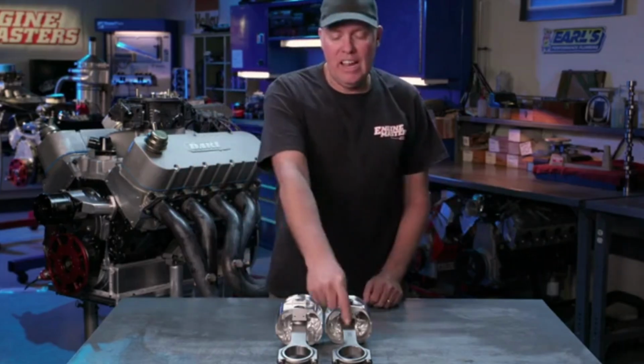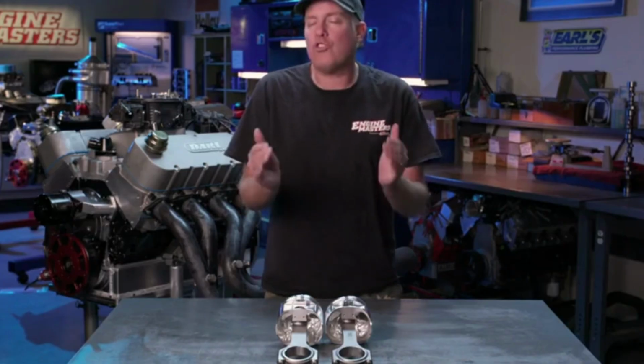What is rod ratio? Simply, it is the length of the connecting rod divided by the stroke of the crankshaft. It seems really simple, right? However, if you read about engines at all, you will find out that people think it is like the most critical part of engine performance. You'll find guys who are designing their whole camshaft and cylinder head package around the length of the connecting rod.